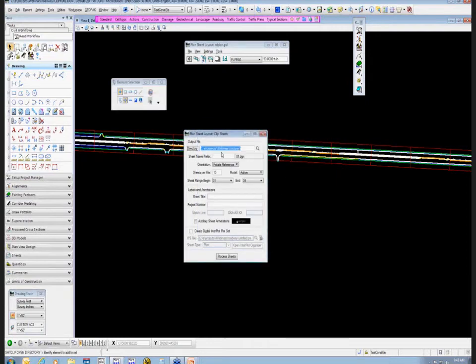In my roadway directory, I have a sheet prefix. This is the file name, which is PLPRRD, and you see I've got 01 is the DGN, and I'm just going to create. I'll go ahead and create just the one file. If I use rotate reference, I can place more than one sheet per file, because what that does is it places the sheet and then it rotates all of my references to fit within the sheet with the same orientation.